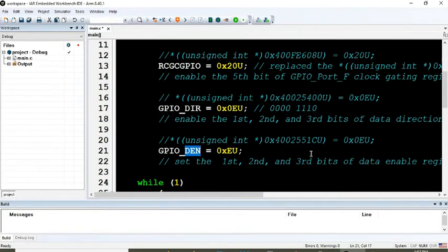To specify whether these 3 pins will act as digital input output or analog input output or any other purpose. So basically, it is just digital input output. So therefore we are entering 0x again, 0 0 0 0, 1 1 1 0. Now does it make sense that we are making all three pins digital pins?